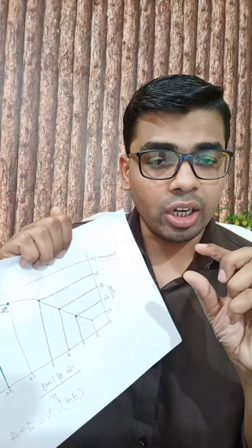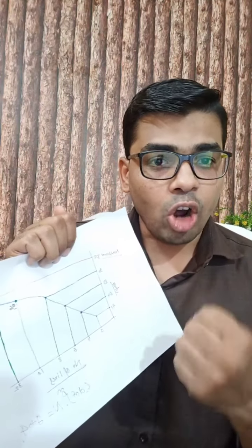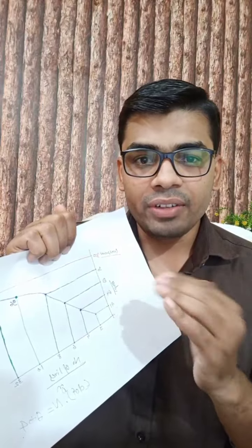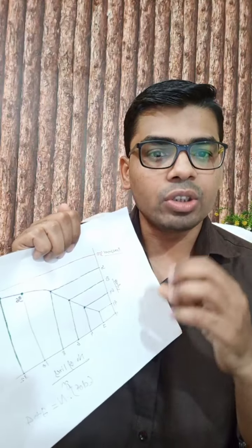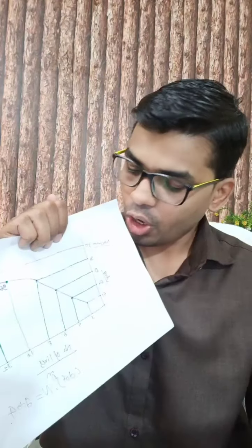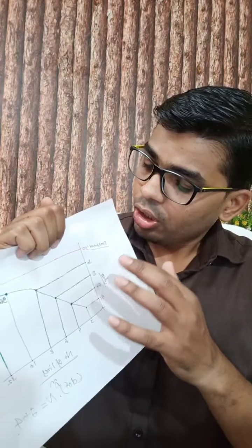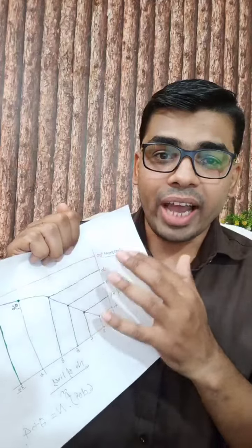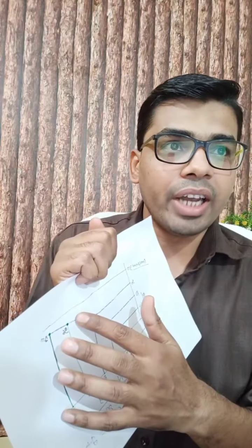Also, if you are considering frictional contacts, right? For master and slave surfaces, try to keep a good balance of fine mesh, or maybe a similar kind of mesh order.